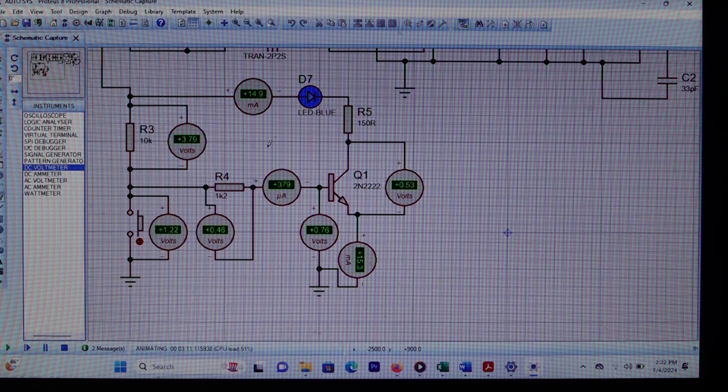So you have the simulated base current, the simulated collector current, and the simulated emitter current. You can prove it, it's just simple algebra. Take the collector current plus the base current and equate with the emitter current to check whether the theory has been verified or not.